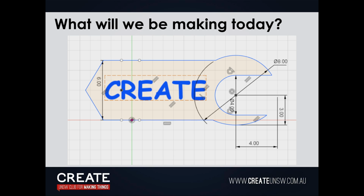Next you select the mirror line. It asks you if you want to select it. You make sure that is actually highlighted before you select anything. So mirror line, you click on that, click on that, then you will do that. Now that's mirrored on the other side. You hit OK. We go trim again, trim that off, and we trim that off.